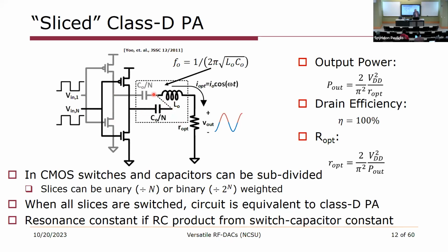The last thing to note here is that from the perspective of the inductor here, when we look backwards towards the capacitor and switching array, all of the capacitors always see a constant connection to a fixed voltage, in other words, a virtual ground. So all the capacitors in parallel add up to the same capacitance as they would if we hadn't done this parallel operation. In other words, the resonance doesn't shift, so we don't have to worry about detuning the circuit.